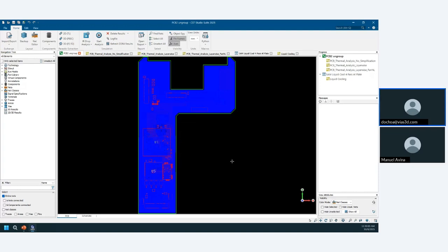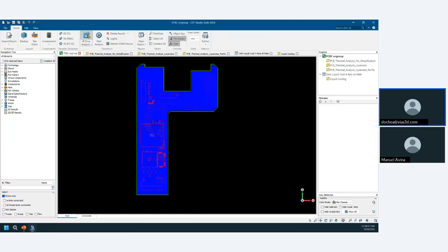Thank you. Perfect. So I have 2 simulation projects in here. Just to show you how this workflow works, I have a simulation of a PCB. This is coming directly in PCB Studio. I imported this project as an ODB++, and I am doing an IR drop analysis in PCB Studio, so I get the DC losses and move that to a thermal project.